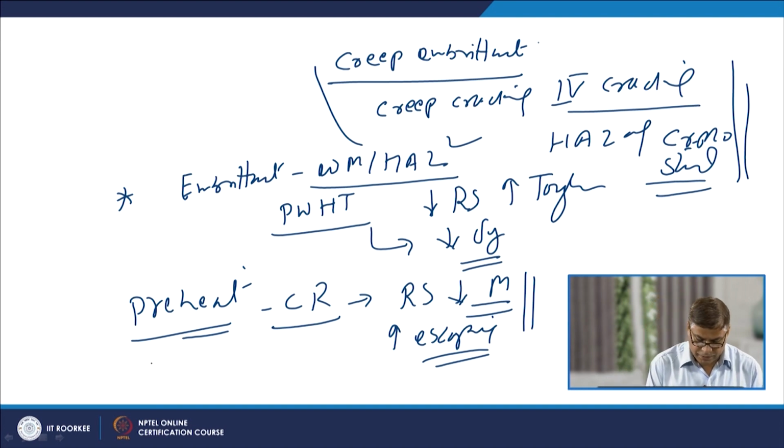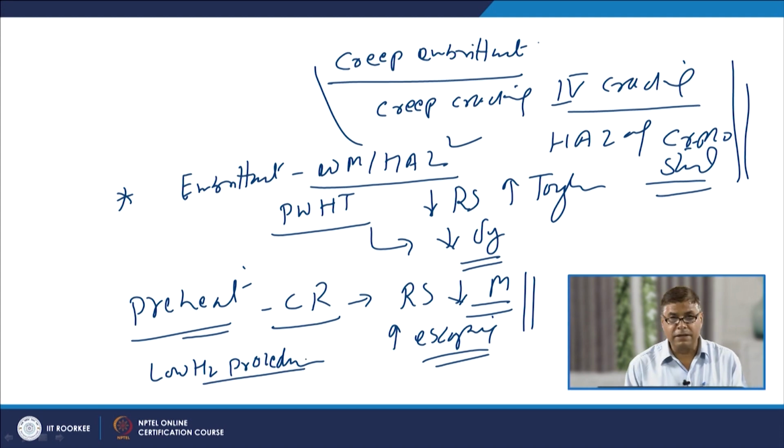And if the low hydrogen welding procedure is adopted, then certainly the amount of preheat to be used in order to control the hydrogen induced cracking will be reduced.